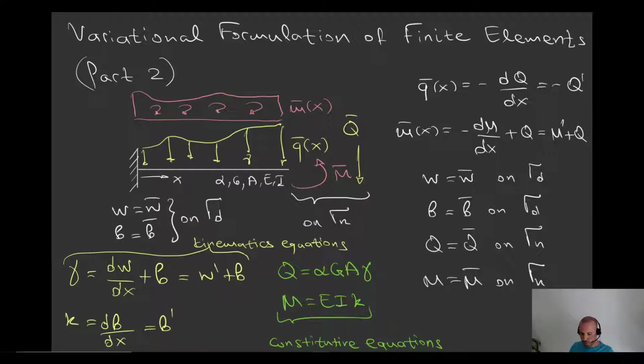Okay, now the differential equation of the problem is laid on the right of the slide, where we can see firstly the equilibrium with respect to the vertical forces. The second equation accounts for the equilibrium with respect to the moment. And the equations afterwards are nothing else but the boundary conditions. So in this case, we actually have boundary conditions which are applied on the primal unknowns of the problem, the vertical deflections and the cross-sectional rotations, and boundary conditions applied on the Neumann boundary, which are basically boundary vertical forces and boundary moments.